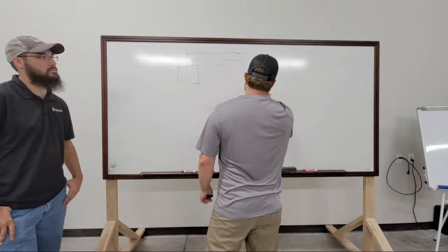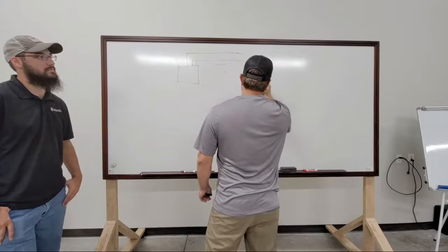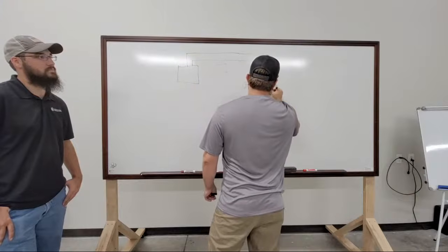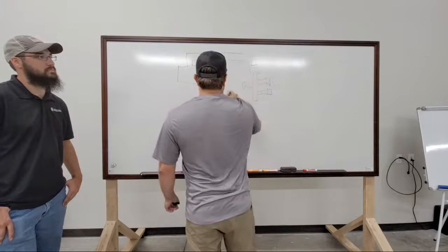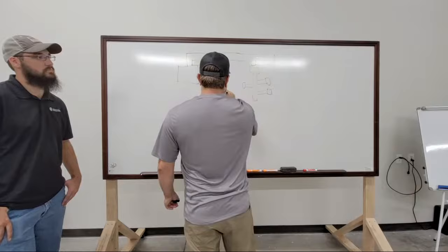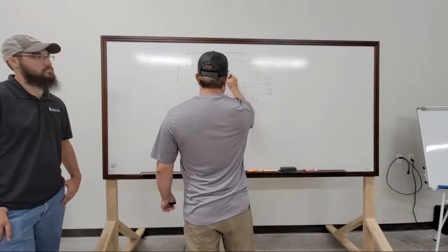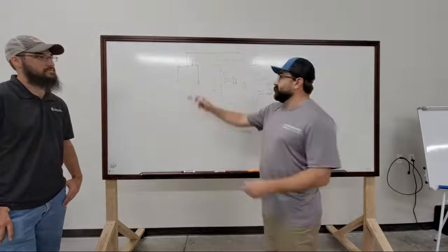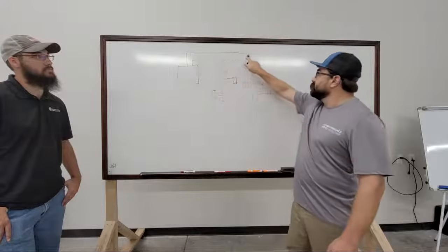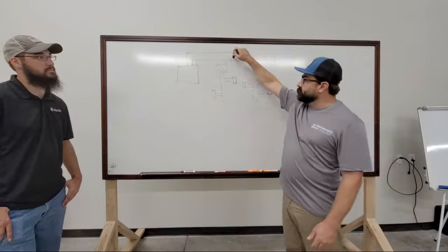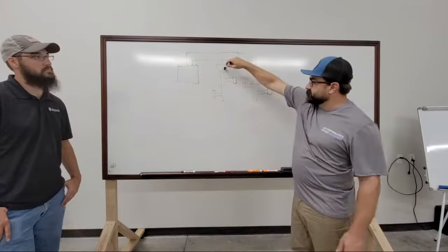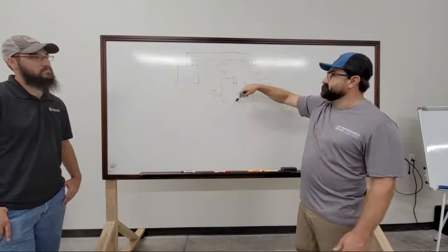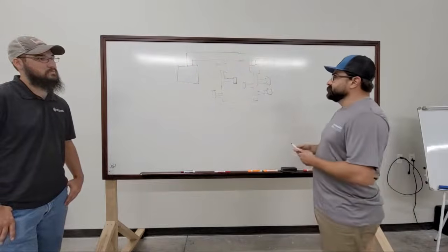Look, I said don't mind the drawings, okay? Okay, so this would be your air handler providing air to the ductwork. From the ductwork, we tap off and we have terminal devices. These devices meter the airflow to the space to control the space temperature, basically.